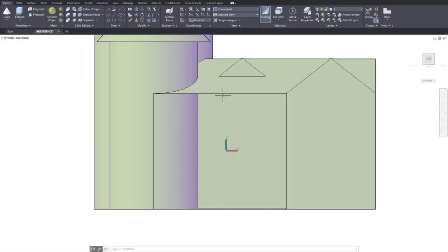It's very important that I draw the center line, so I'm going to go to the line command, see if I can find the center point. Okay, this is good. And I'm going to turn on the ortho mode so that I draw a vertical line. Good. Enter. And center line does not show for some reason.